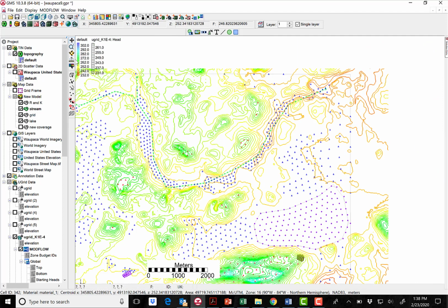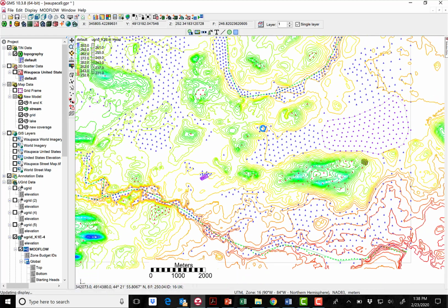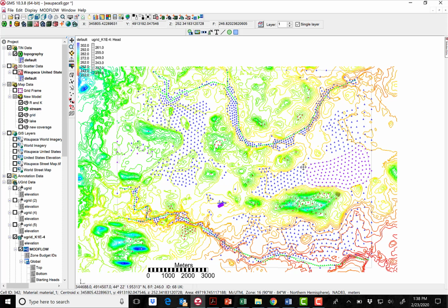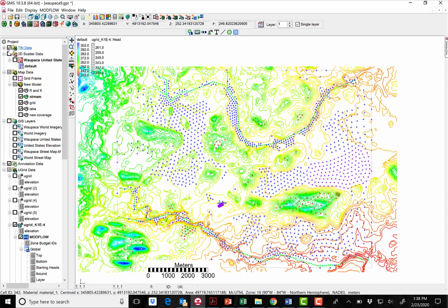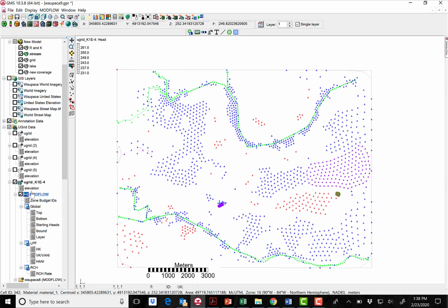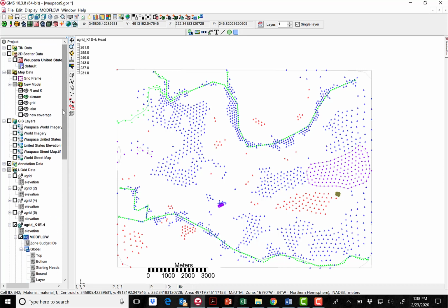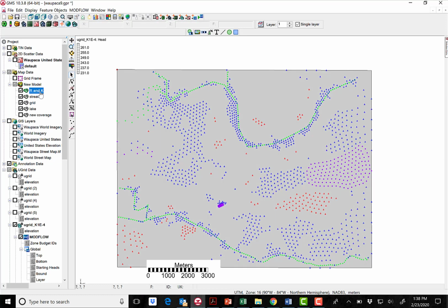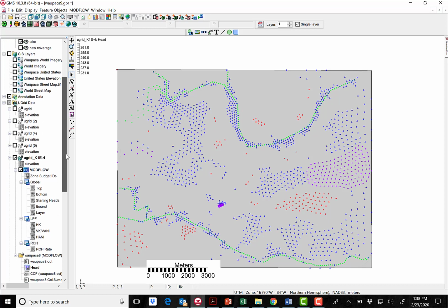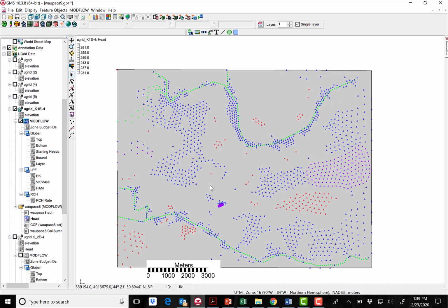Okay, so I think this model looks pretty good as a first start, but with all these flooded cells here, the heads are a bit higher. So what I'm going to do is run this model again, copy the grid and set up another MODFLOW, and then change the coverage here to increase the hydraulic connectivity. That was done because I wanted to drop down the hydraulic heads.